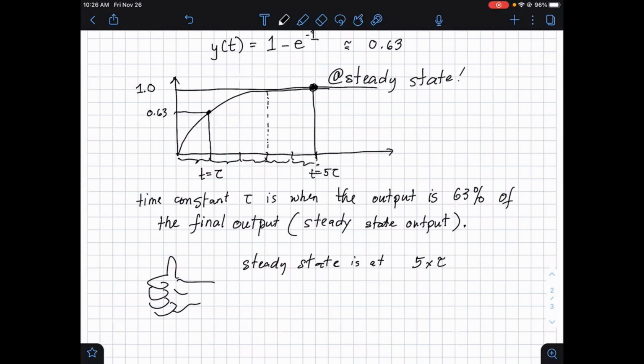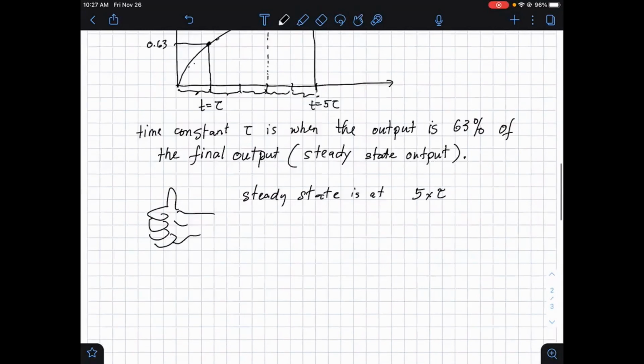Why is this necessary? Again, bakit ito ulit necessary? I must emphasize, when you do an input-output calibration curve, you have to measure the output at steady state. Never measure it maaga pa, because you are not measuring the full value or the full output of the system. Okay? This is the reason why.